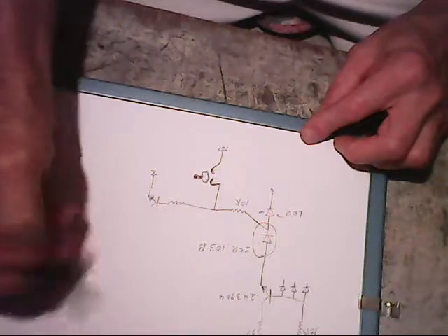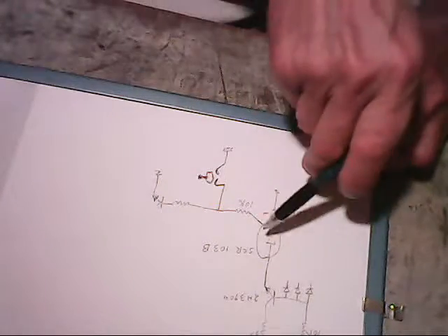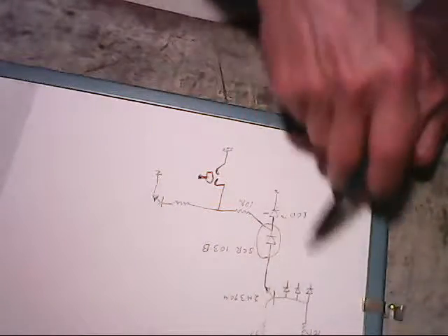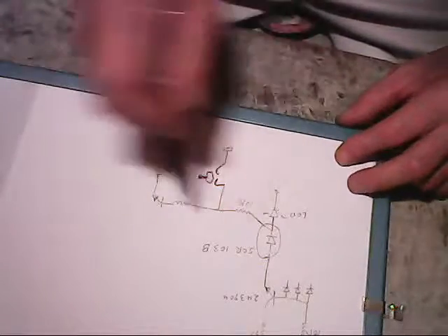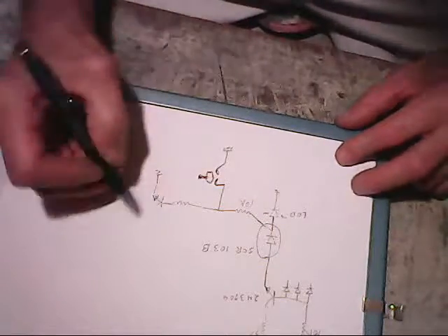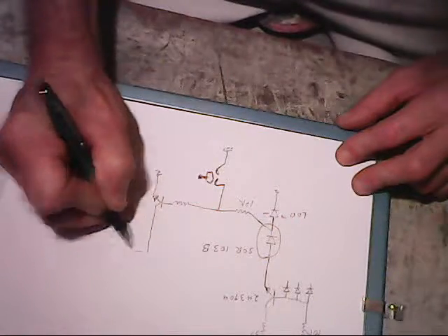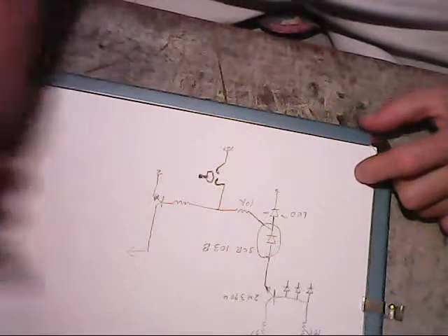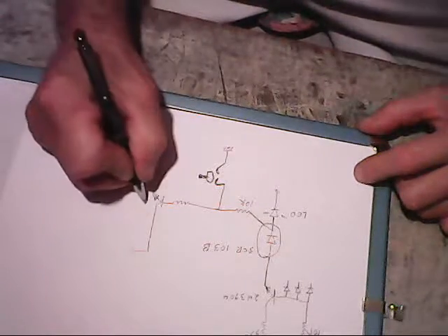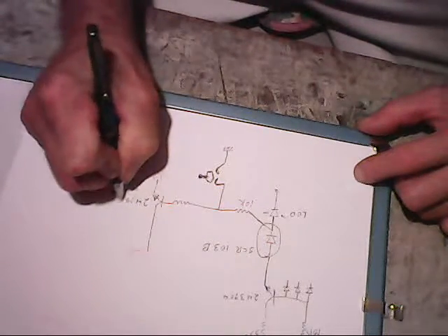The load is going to be above it, and that load is going to be these latching cells here that we're building. We're going to build 3 of these, and what we need to do is turn this transistor on, and it's going to send a negative signal into the diodes of the other latches. That's all we need: 1 NPN transistor, 2N3904 again.